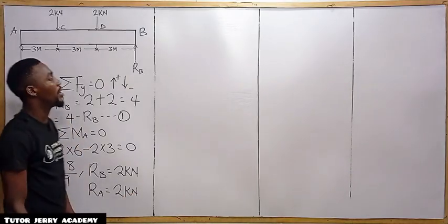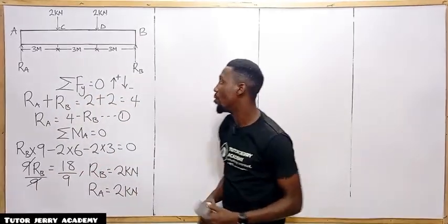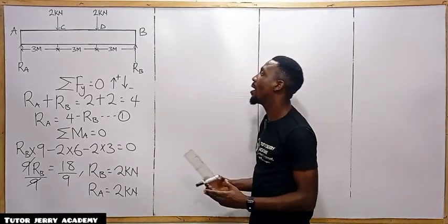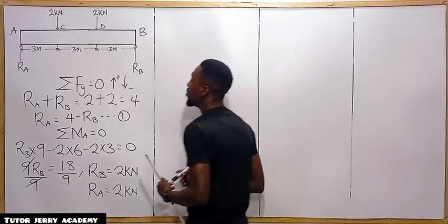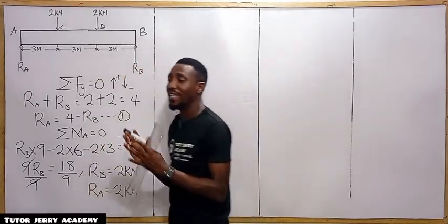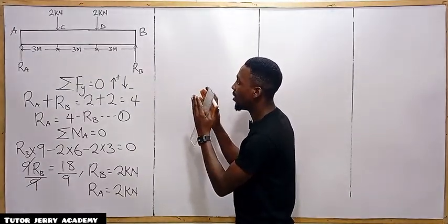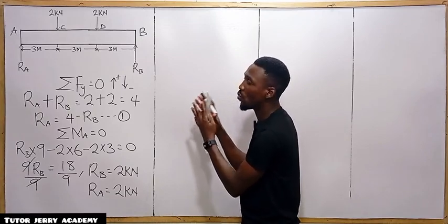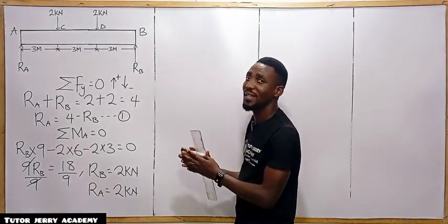Now we are going to start with the sectioning method. For us to apply the method of sectioning, you must first know how many sections you are going to need to solve the question completely, since we are drawing shear force and bending moment diagram.